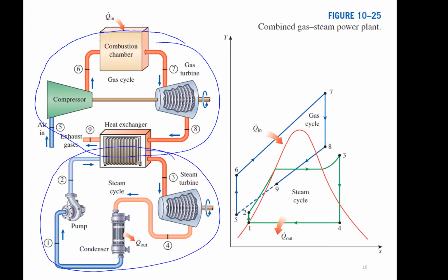So you have chapter 9 and chapter 10 going on here. So you have the Brayton cycle, and then the heat that would normally get rejected to the atmosphere in the Brayton cycle is used for the heat in on the Rankine cycle. So then you only get heat in right here externally, heat out of this condenser here, and then heat out right there. Okay, so there's just this heat in and those 2 heat outs.